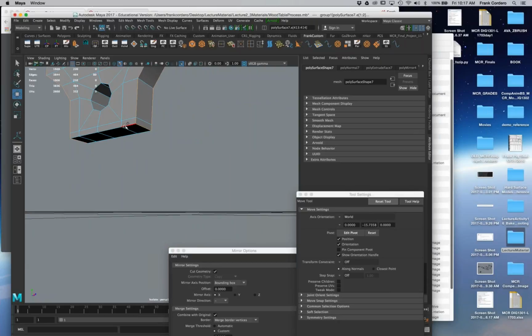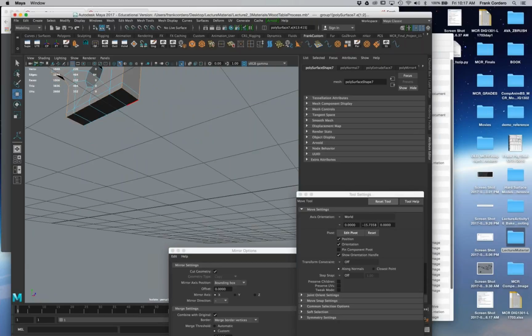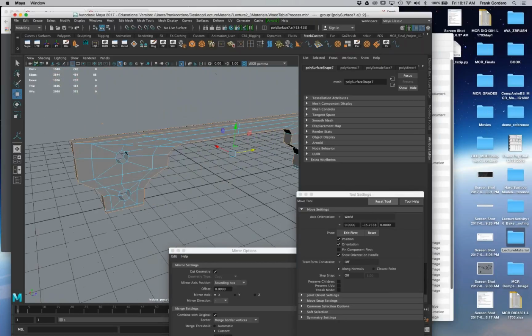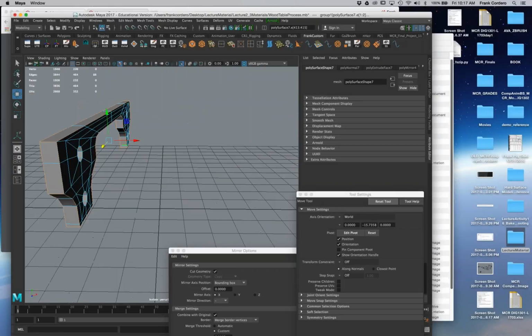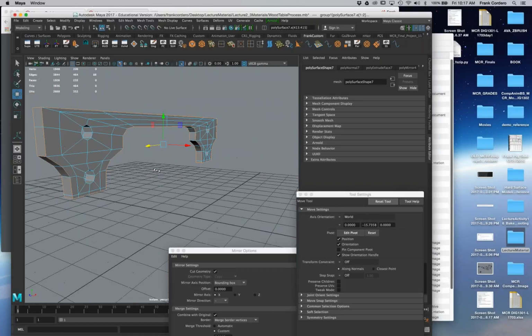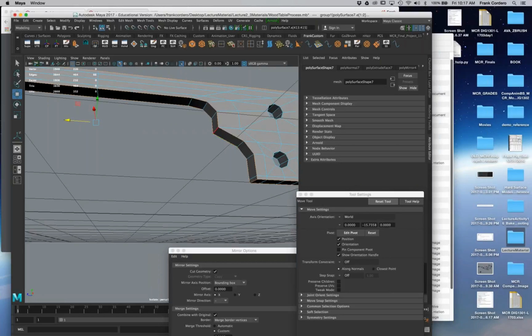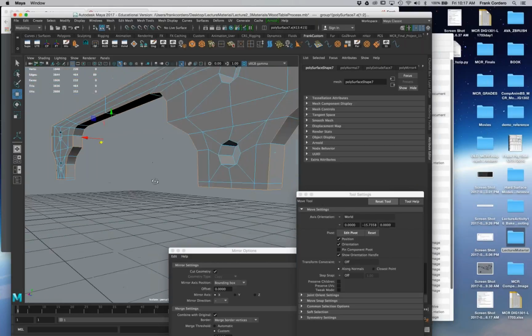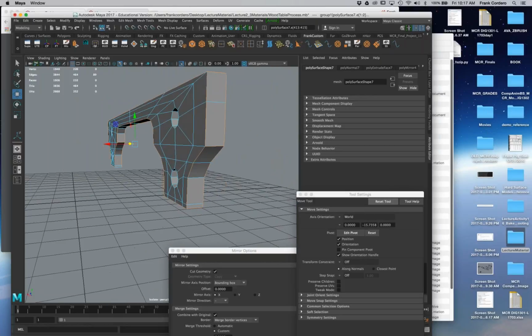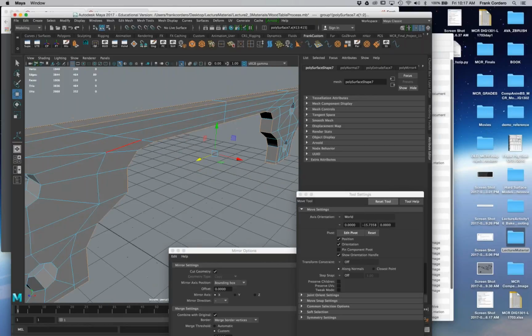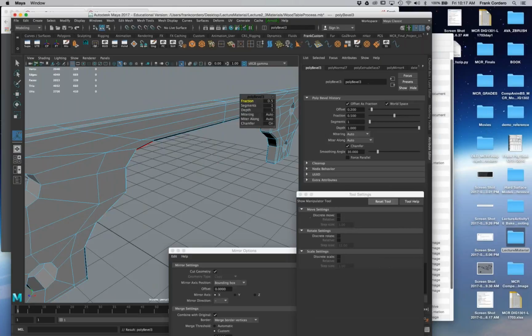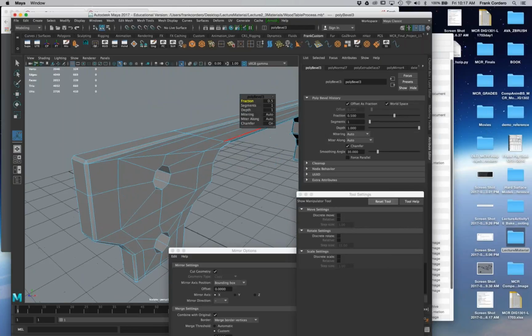Now I'm going to save the hole cuts for a second pass on their own because I think they're either sharper or more blended in. All right. So I've got all the edges that I think I need selected. Oops, missed that one. Cool. So I'm going to Shift right click, bevel edge.